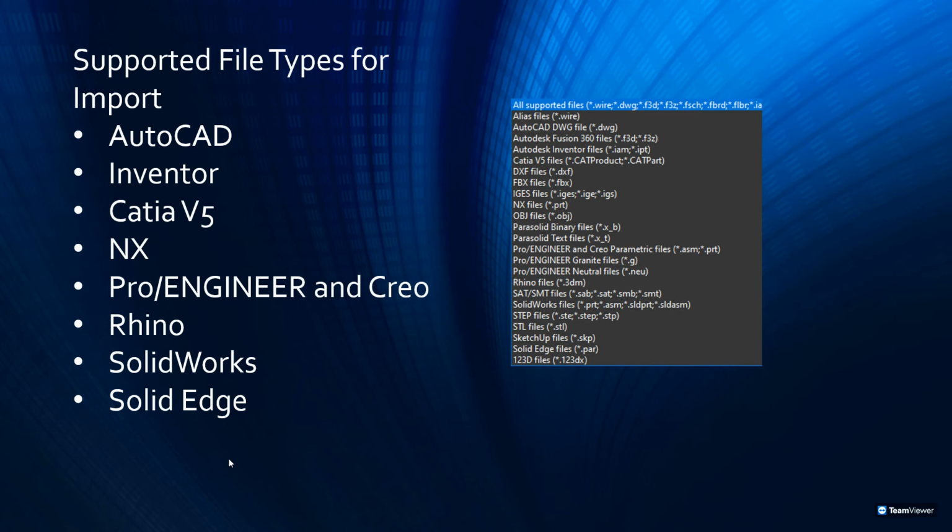If you don't have those, you can see all the files on the right-hand side that you can bring in. So things like STEP files, STL, SAT files, Parasolid files, OBJ, IGES. Those are all the non-specific to a CAD software files. But as you can see, you can basically bring anything you've created from any other package into Fusion 360, apply your materials, and go and render.